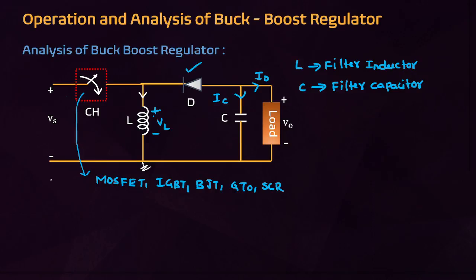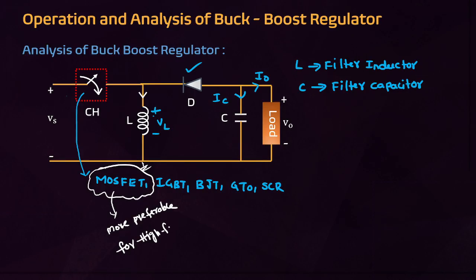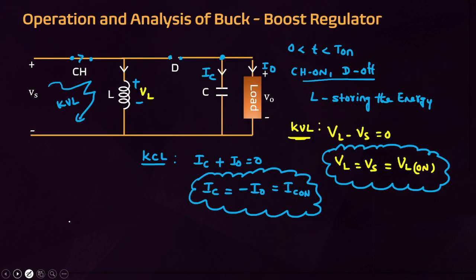The switch may be any device. It may be MOSFET, IGBT, BJT, GTO or SCR, based on the frequency of application and the power application. But MOSFET is more preferable for high frequency, friends. Very important, MOSFET is more preferable for high frequency and SMPS applications.